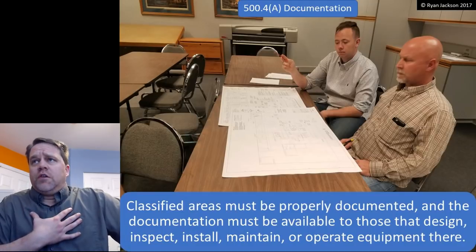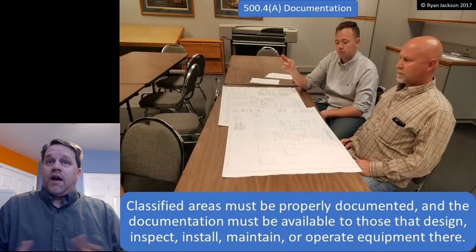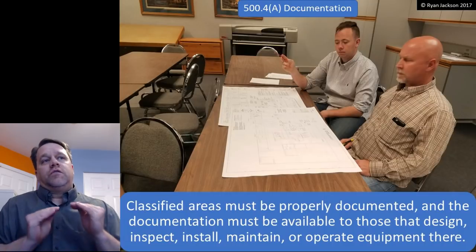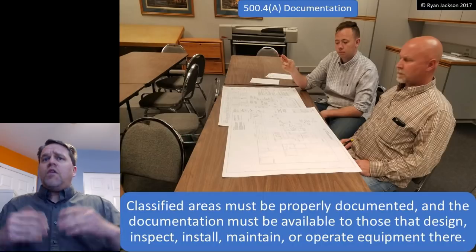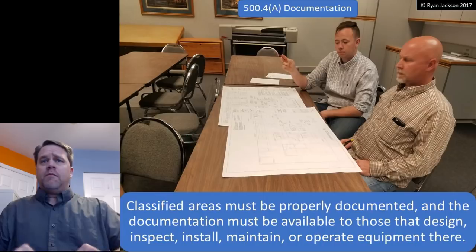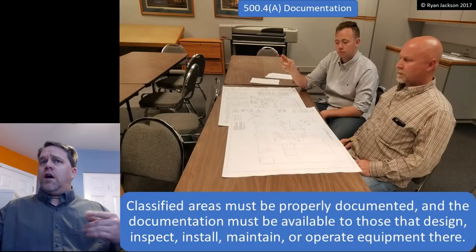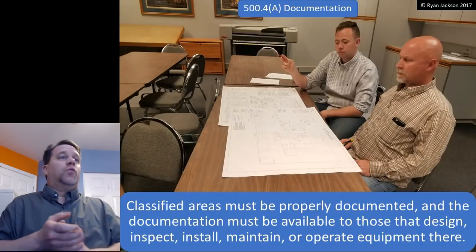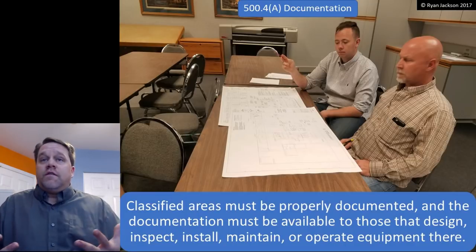When I was an inspector, this was easy. If you submitted plans for a building that had a hazardous location, I did not issue a permit until the hazardous locations were properly documented. I need to know what class, what division, to what extent, as far as the square footage of the area. From the floor up, how many inches? From the ceiling down, how many inches? Near the door, how far out does it go? What's the group rating of the chemicals? What are the chemicals? What's the auto ignition temperature? I need to know all of that information.